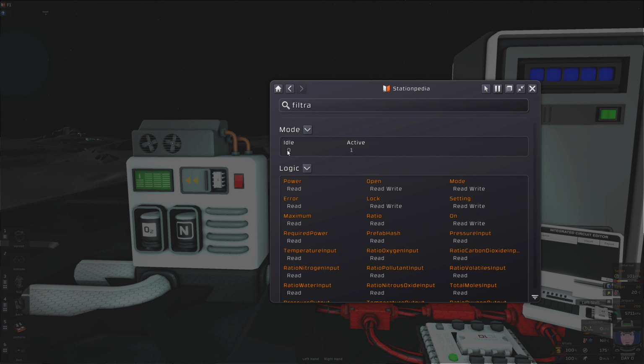This is necessary, for example, if you're running a microchip in there, because if you think this thing has filtered enough, it's time to stop the filtration process, you cannot really turn it off with a chip. I mean, you can, but then the program has ended. It can no longer run. There's no more power. But if you instead set the mode to idle, then the device will stop doing stuff, but it will still be powered. So that's the way to go.